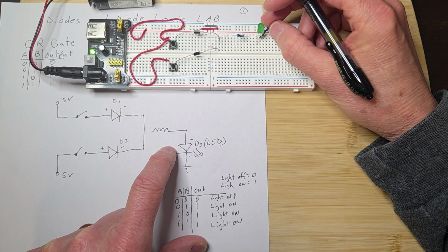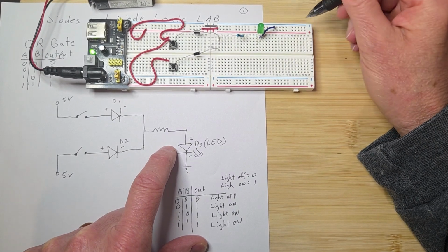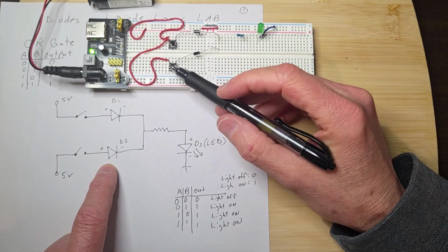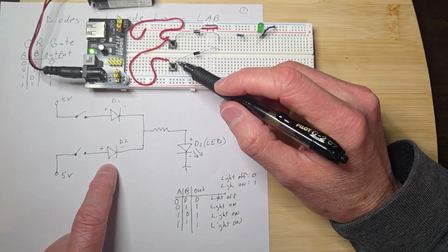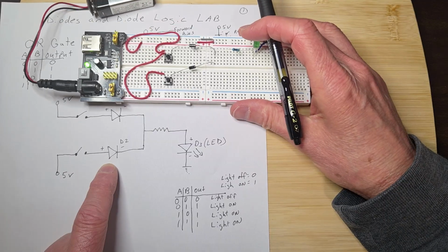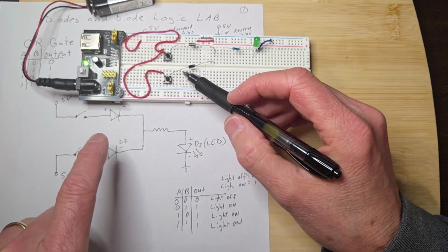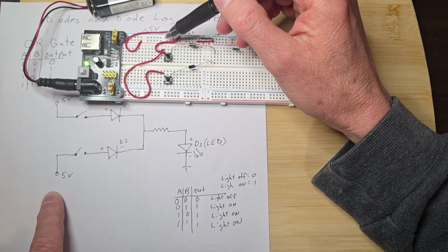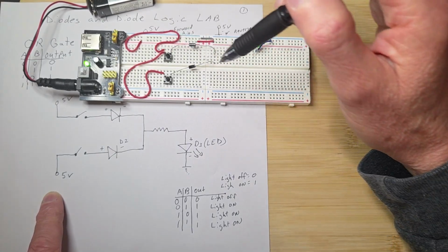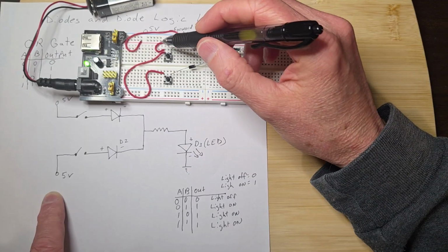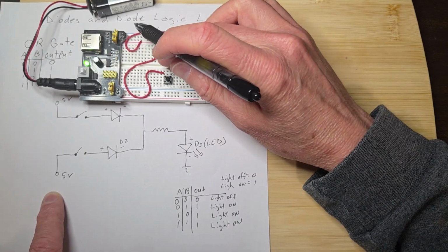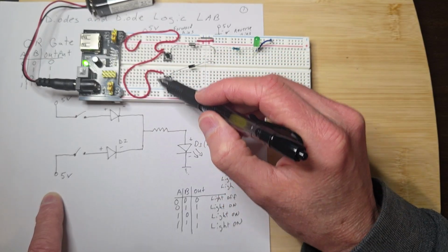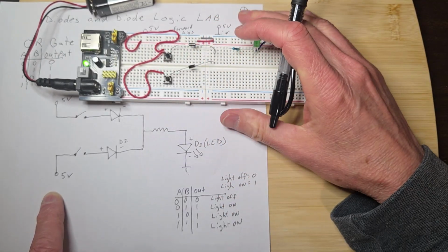I had to use blue wires here because I didn't have any black wires, but it kind of matches that rail color. So then we have input B. That was input A. Input B is right here, and really what we're doing is just tapping into that same wire on that side of the switch, and then running the 5 volts here. So instead of running it from here to here, I'm just tapping in and running it here.